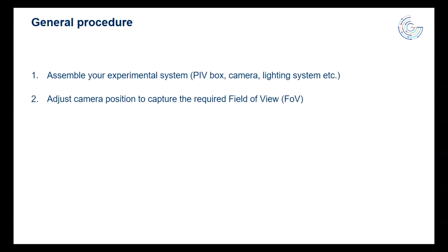And as I said, if you're using machine vision cameras, you're going to have to link back to the control room, go and have a look, adjust it a little bit, go and have another look. A pair of walkie-talkies and a couple of people often come in handy for this and make the process much quicker. Once you've got the camera position right, you then want to arrange the lighting.